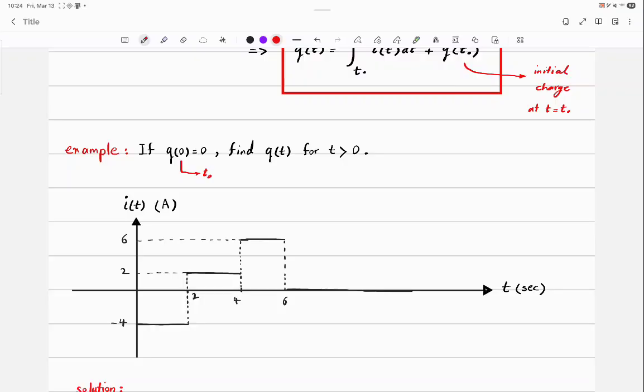Okay. With everything easy that we learned, there should be something painful as well, right? So we have independent sources, and now we have dependent sources. What does it mean? It means that they behave the same as usual sources in the sense that they provide current and voltage to one branch or 2 points, but they are dependent on some quantity in some other points of the circuit. For example, let me talk about this example just a little bit, and then I will be back to the notes.